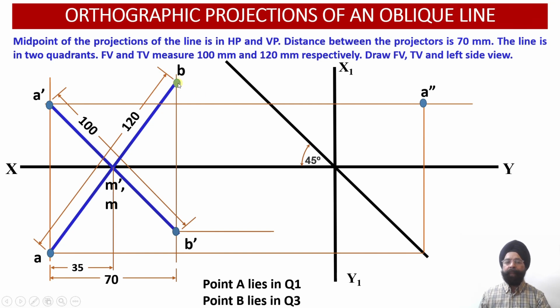So from point B, we are going to draw a horizontal projector line in such a way that this projector will be extended such that it meets the transfer line which had been drawn earlier over here. The moment it intersects with this particular transfer line, one point corresponding to the point B of the plan has been obtained onto the transfer line over here.